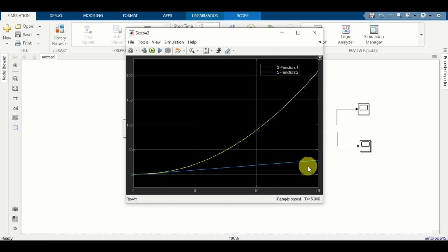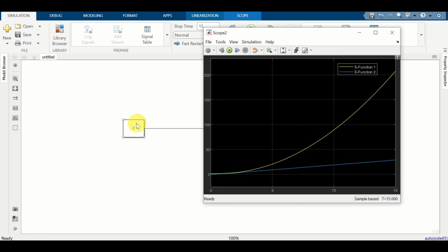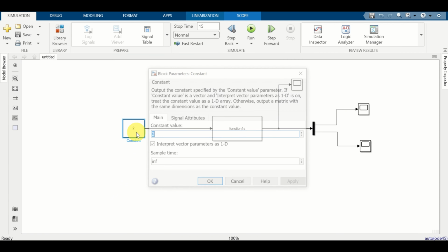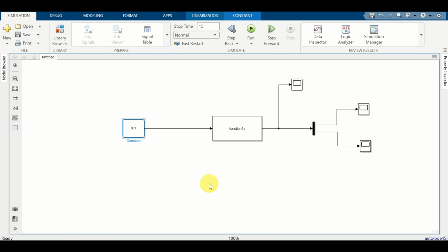Well, is this realistic? This is a good question. It looks like over here that we have specified a large value of this force, and this might lead to significant rotations of our pendulum. So let's decrease the value of the force over here. Double click here and let's specify the force to be equal to 0.1 and click on Apply and click OK.